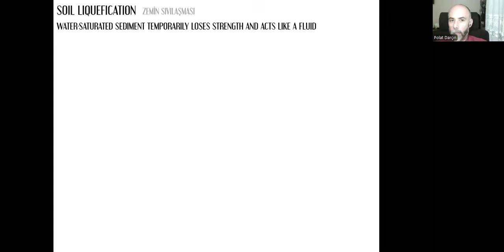And if there is soil liquefaction, zemin sıvılaşması, it means that water-saturated sediment temporarily loses strength and acts like a fluid, not a solid, but a fluid. Here is an experiment made in Nide University Civil Engineering Department. Let's take a look at that.